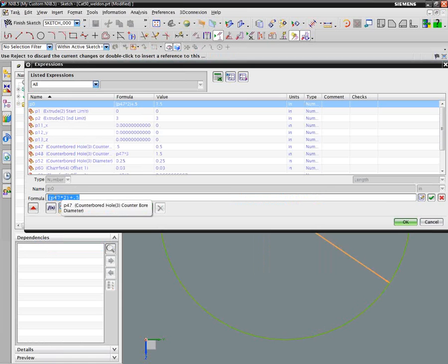And again, it's based on P47, the diameter of my bore. I multiplied it by 2 and gave it a nice round number: I'm going to add a half inch on the diameter. So, you know, that just kind of looked right. You could go and look at some different manufacturers and try to extrapolate some formula, but for our purposes here, this kind of looked right.